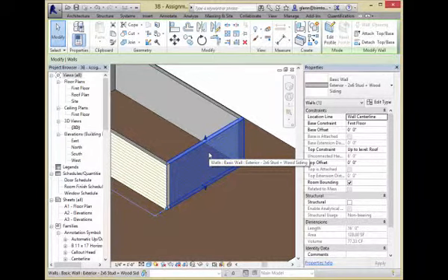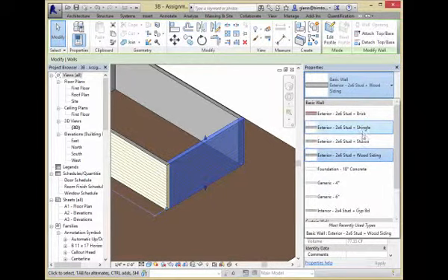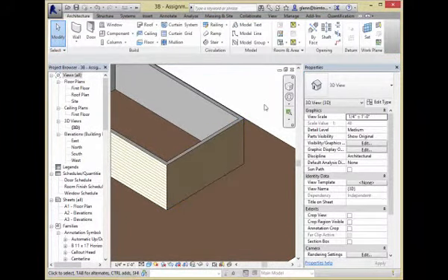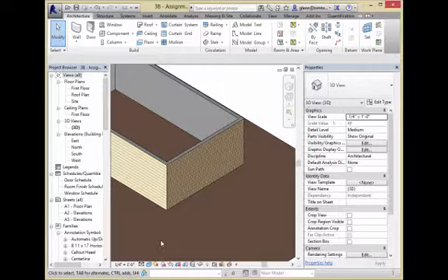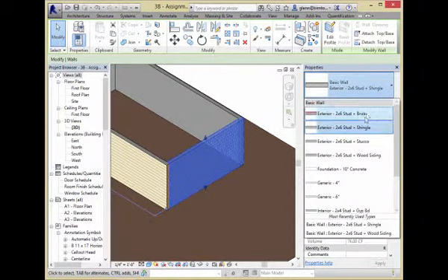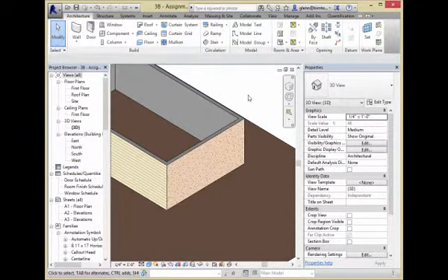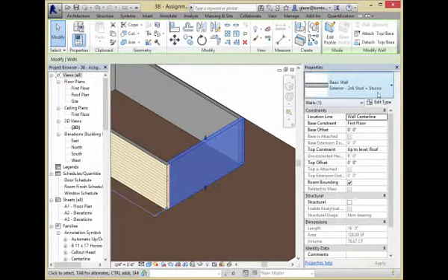They have this kind of yellow appearance, these horizontal lines running across. That's supposed to look somewhat like siding. If I decide to change one of the walls to a different type, like shingle, it'll apply a slightly different visual property to that. See if I can make that consistent colors. That might be easier for you to read. So that's a siding wall, that's a shingle wall. If I make that stucco, you'll see it has a slightly different visual appearance. So one of the things that you get out of the different wall types is the visual appearance. We'll also get the thermal properties. Okay, change that to brick.